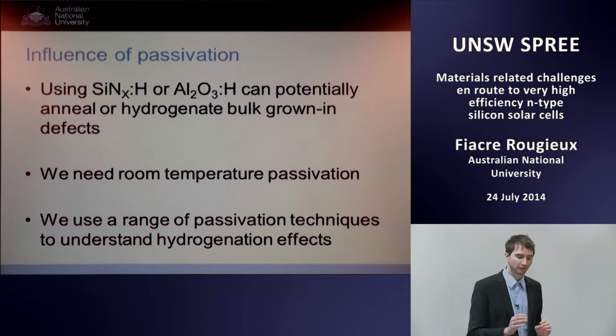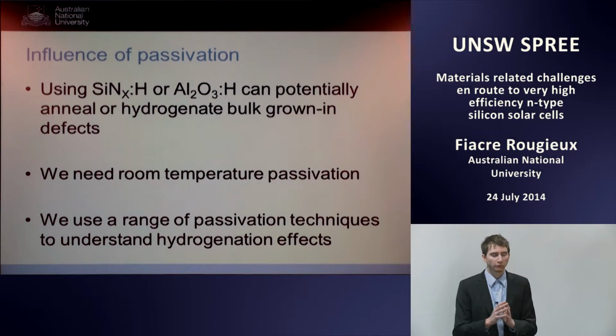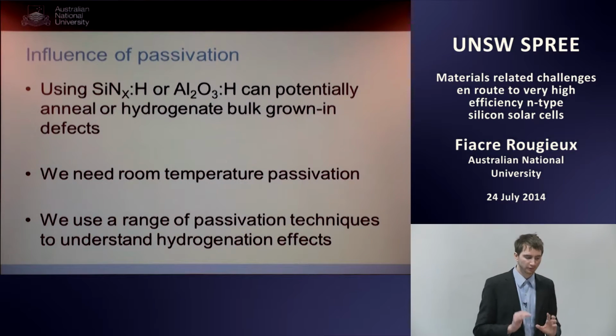I have to note here, again to emphasize, that we're talking about really small defect concentrations, 1e10 per cubic centimeter. So it doesn't require much to hydrogenate this defect or to deactivate this defect. That's why we have to be extremely careful when looking at these defects.